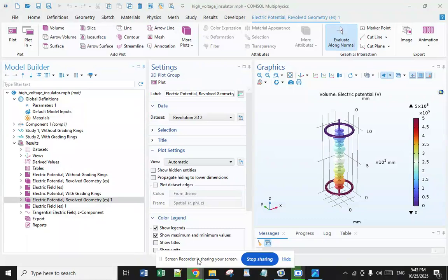These elements have different characteristics such as dielectric strength, dielectric rigidity, mechanical strength, and corrosion resistance. Moreover, there are different types of insulators such as glass, porcelain, epoxy resins, and silicone, which can be used depending on the environment in which the electrical system will be used. By choosing the right insulator, the safe and efficient operation of the electrical system can be ensured.